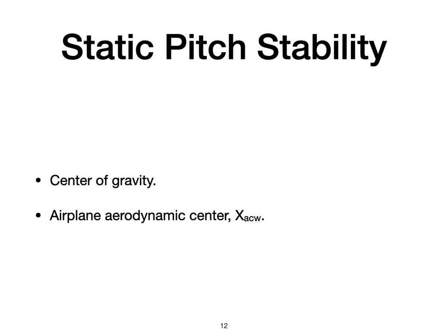For any aircraft, there is a center of gravity location that provides no change in pitching moment as angle of attack is varied. This airplane aerodynamic center, or neutral point XNP, represents neutral stability and is the most aft center of gravity location before the aircraft becomes unstable.